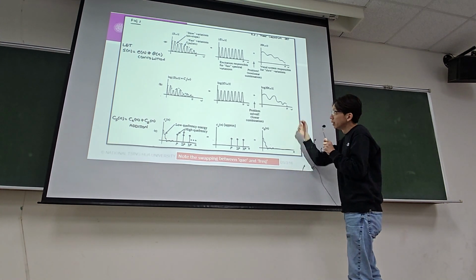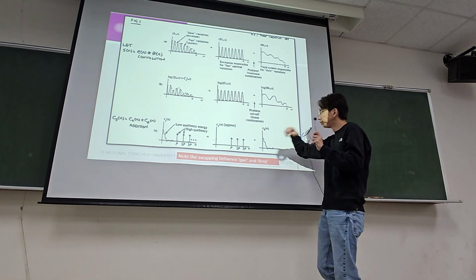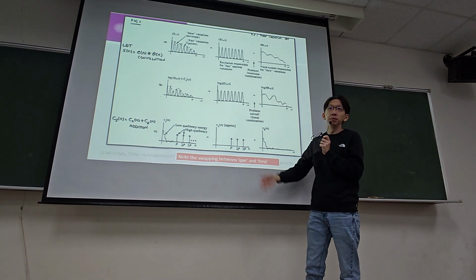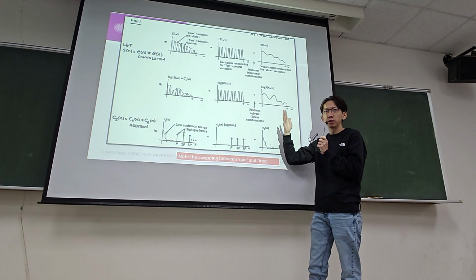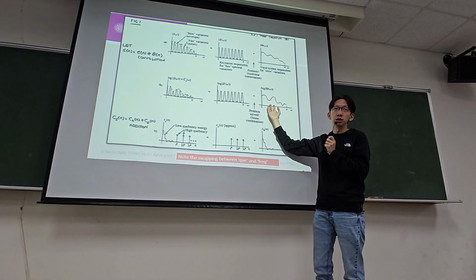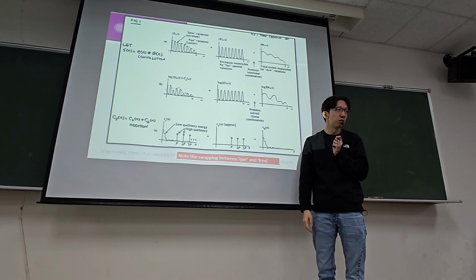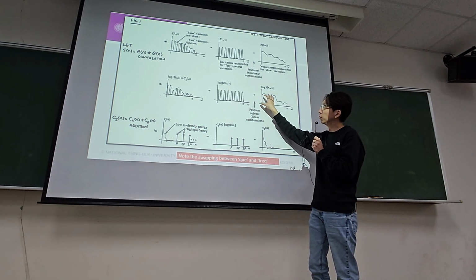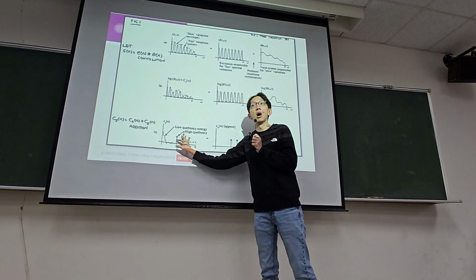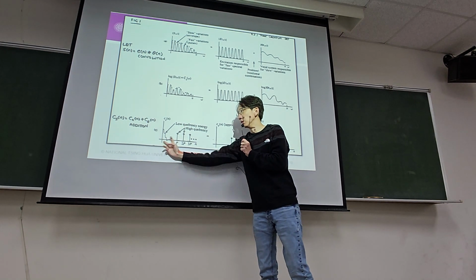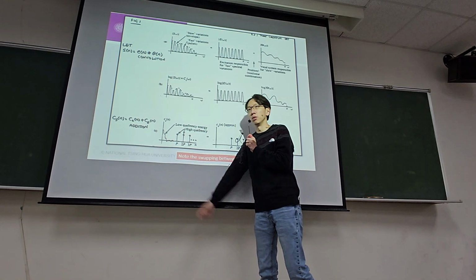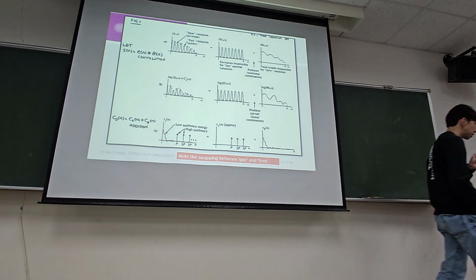Now we just need to find a new domain that makes the fast varying signal and the slowly varying signal nearly separable. We already know how to do that. Imagine a time domain signal with high frequency plus low frequency. What you need to do is take another Fourier transform, another spectrum transform. You move the slowly varying part to the beginning and the fast varying part to the upper part. Then you just need to design your filter, in this case called a lifter operation, to lift out the part you want. That is this kind of process.